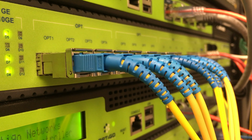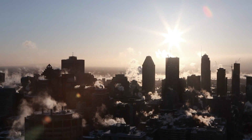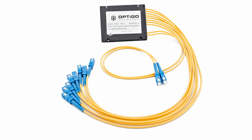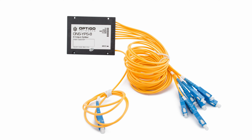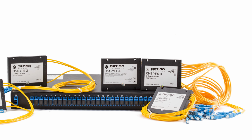One of the powers of Optigo Connect Spectra is the ability to connect several passive fiber splitters to create a low-cost and scalable large network, whether that's for wide buildings like shopping centers or tall buildings like office towers. Because different types of passive splitters can be stacked and daisy-chained, it is important to ensure that the overall passive optical network will fit within the allowed range of insertion loss.